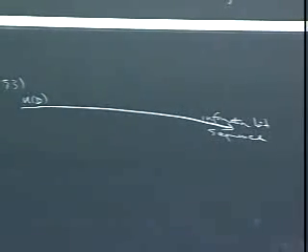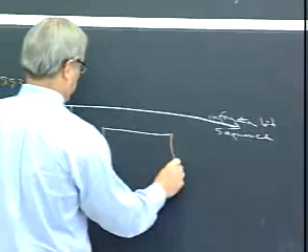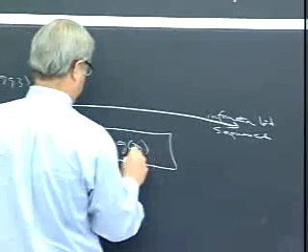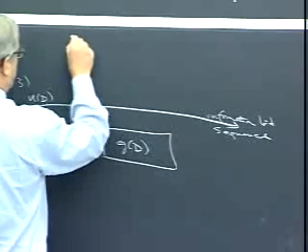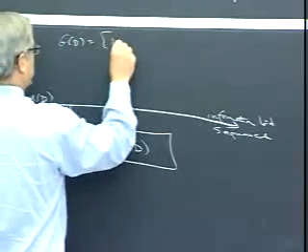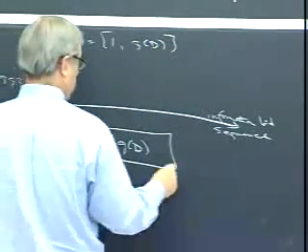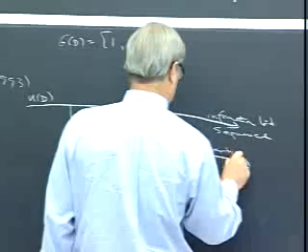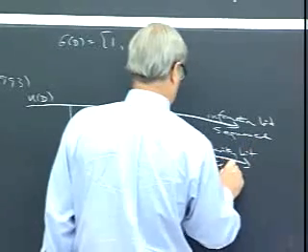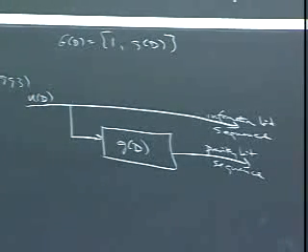Okay, and to make a rate 1/2 convolutional code, all I have to do is pass that through a certain G of D. So I'm saying my generator matrix for the convolutional code is 1 and G of D. That'll make a rate 1/2 code. And this, let me call that a parity bit sequence occurring at the same rate as the information bit sequence. Okay? Easy enough.